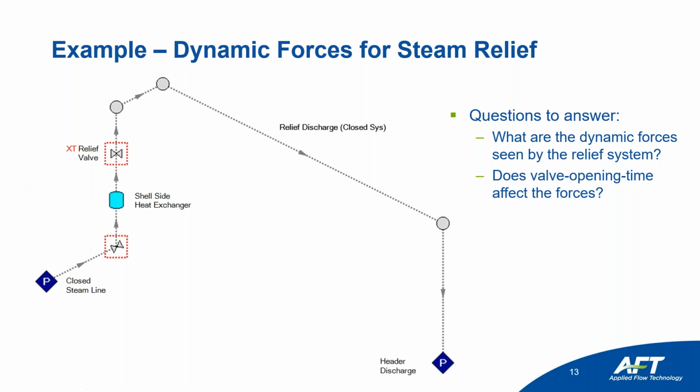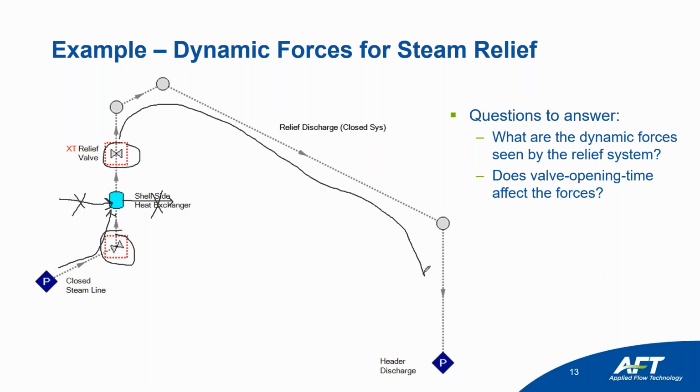So here's the system. What I was saying about the worst case scenario is truly you would have your other gas flowing through this shell side, which could be maybe like helium or something with high heat capacity. Well, we are assuming in this case that those have closed, that while this valve has opened, things close. Part of my control system, again, I am assuming, so I don't even have lines in and out, I just have the tank. The point is, steam rushes in, pressurizes, this relief valve will pop open, and then flow will suddenly surge through my discharge piping into my discharge header.